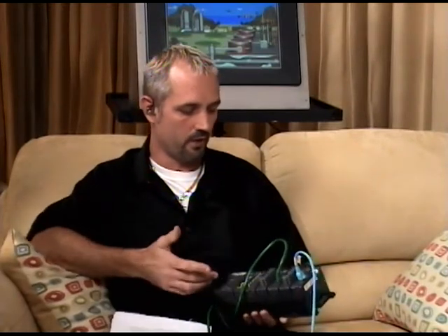Well, if you have Ethernet, I can go from this ECOM down here on the end to a hub, and I can go out to multiple panels. I can still communicate to my PC with it. I can communicate to other devices as well if I need to. So I could network out to some other stuff as well. So it makes life easier and cheaper. Plus, again, reiterate the fact of lower noise susceptibility using Ethernet versus serial cables, plus increased distances.